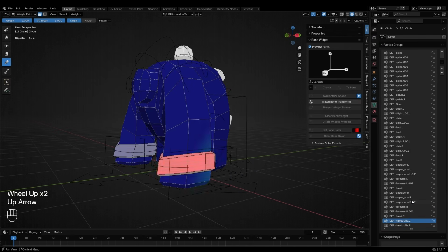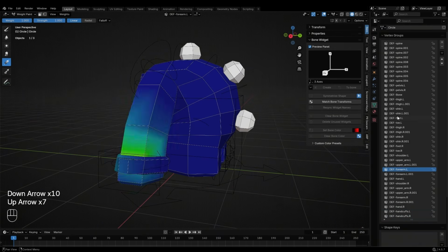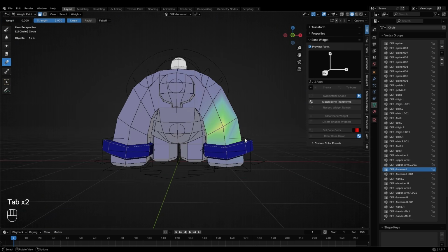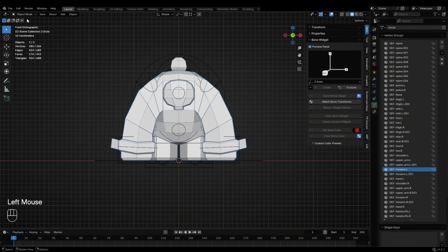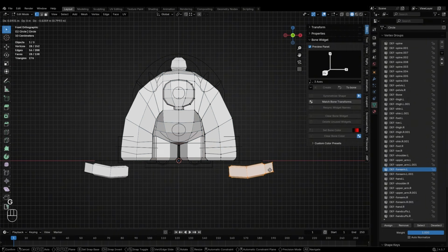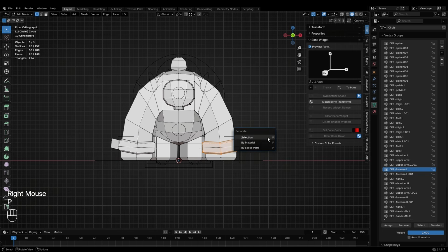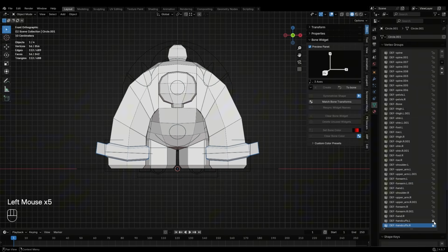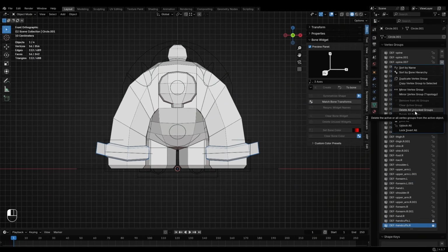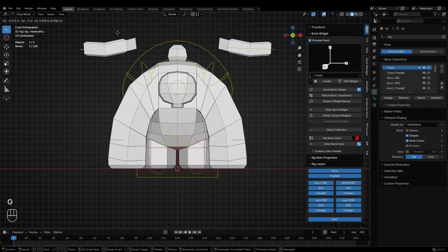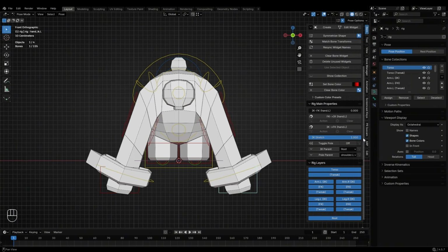Then check the other vertex groups and remove any weight affecting the handcuffs that shouldn't be there. You can clean it manually using the gradient brush, but that can take a lot of time. So instead, we'll remove the unused vertex groups. Before that, separate the handcuffs mesh from the body. Select the handcuffs mesh, press P, then choose Selection. Now select the handcuffs mesh. Then lock the handcuffs vertex group. Then delete all unlocked groups. Then do the opposite for the character body mesh. With this setup, the handcuffs will follow the bones properly. Finally, check and adjust the bone widgets if needed.